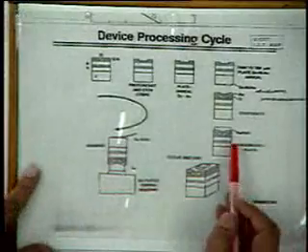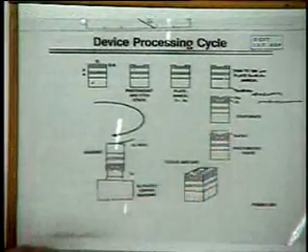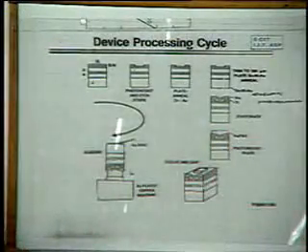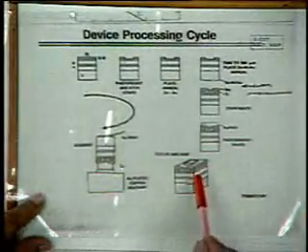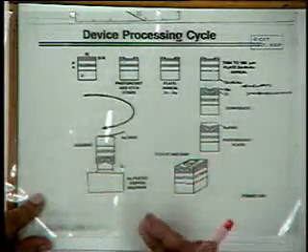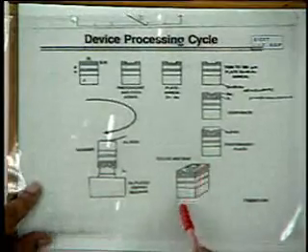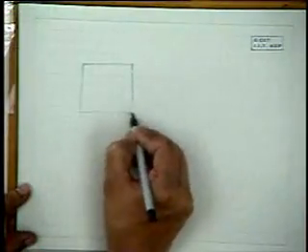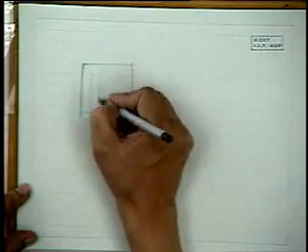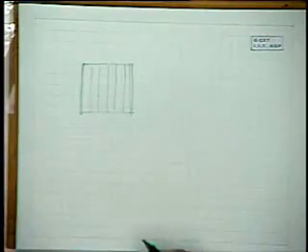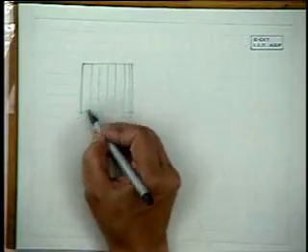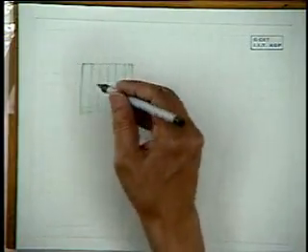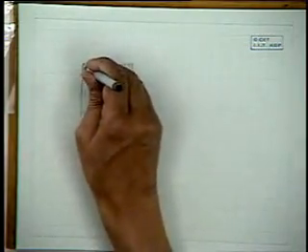If I go back to this diagram, we are here. We can evaporate a gold pad on that. Then we can put the material on a rubber pad, and we can scribe it with the lasers. If the material is like that, we can manually scribe these, and they break up into small slivers, and then if we exert pressure on these, they will cleave